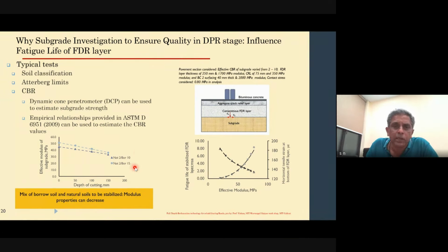Now, in terms of equipment, you're going to be using a reclaimer. The cutting edge of the reclaimer is a carbide-based cutting edge. You need to make sure that it is working fine. In case of water, the water is going to be sprayed on top of the surface before mixing. So the sprays and nozzles, are they working right? The dispersement of water, is it as per what is being shown on the monitors inside of the vehicle? All these things need to be checked.